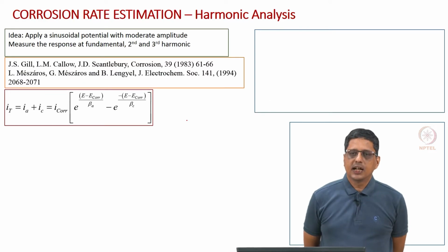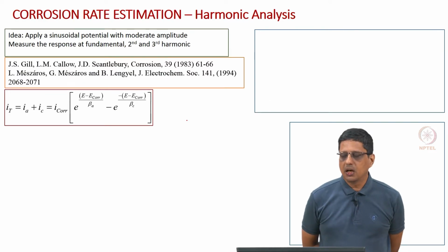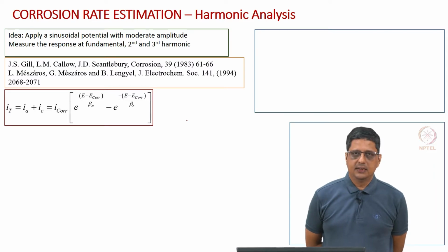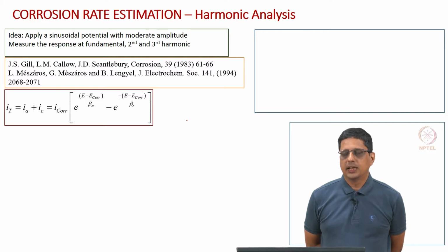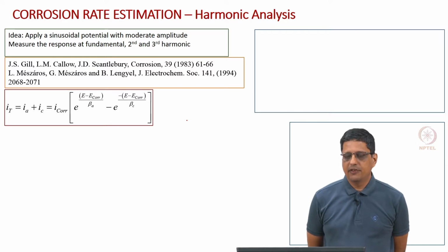Next, I want to describe a technique called harmonic analysis. Okay. The idea is this: we normally apply a sinusoidal potential, monitor the current, and we know the frequency at which we apply the potential. We do Fourier transform, we do phase sensitive detection. In any case, we want to find the component of the current at that frequency.